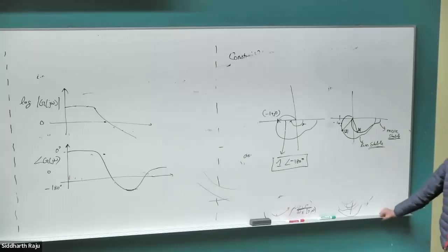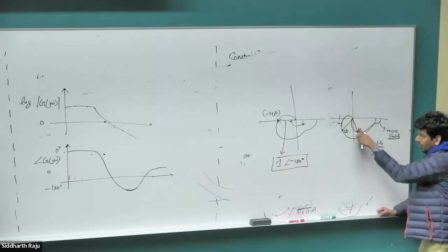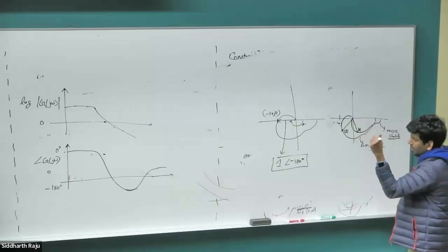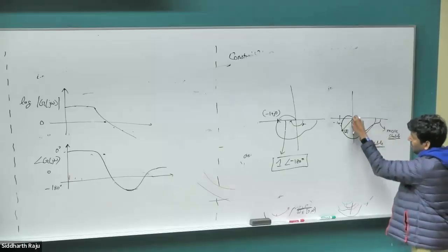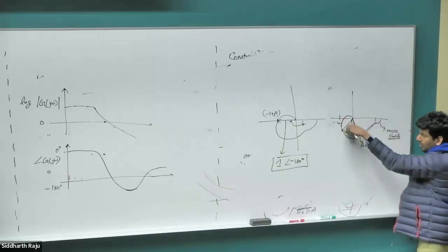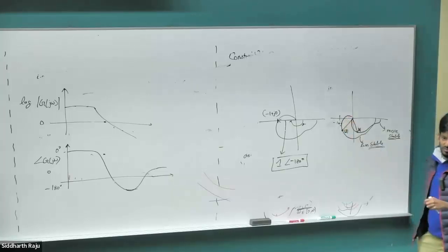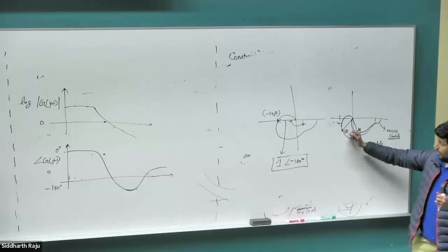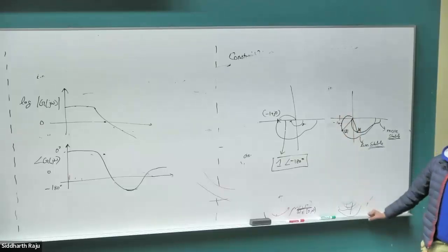Or as our motor keeps running, our resistor, inductors, J, B, all of those change. We saw last week how all of those parameters can change. So the control system that we designed might have started out like this, our open loop transfer function, but our open loop transfer function will change over time as the motor heats up, core saturates, all of those. So it can end up going to this location where it's much closer to -1 plus j0. But if we started with a controller that was already putting it here, as the motor parameters change, it can push it around and make the system unstable.